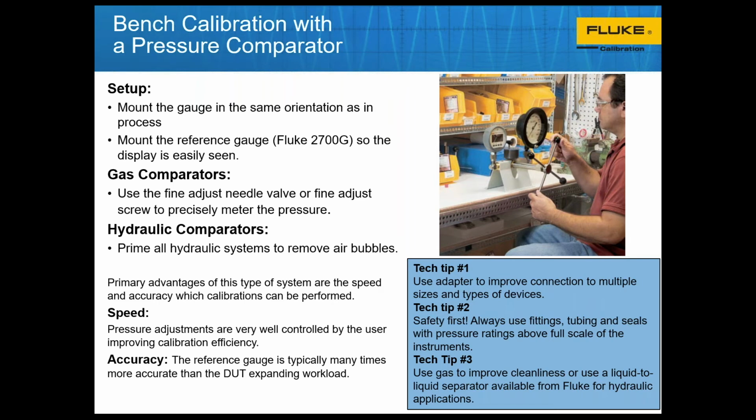This particular person is doing something with a very simple gauge comparator. So what you do is you have a high accuracy pressure gauge as your reference standard, and you compare it to your unit under test, and you have the ability to turn this wheel and make adjustments for pressure and then some vernier adjustments, and you're constantly making a comparison between the two. Again, probably one of the simplest, easiest ways to do a calibration. And the nice thing about them is they're not super expensive. So if you have the opportunity to do calibrations like this, it might save you a bunch of time.